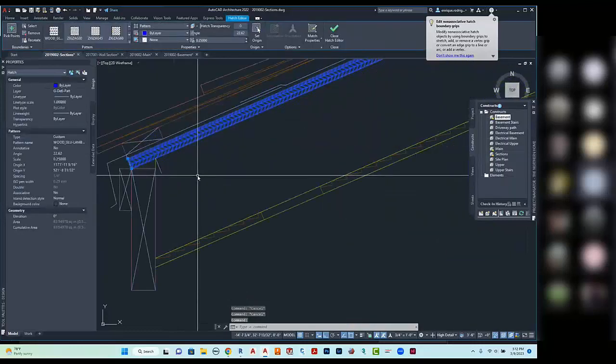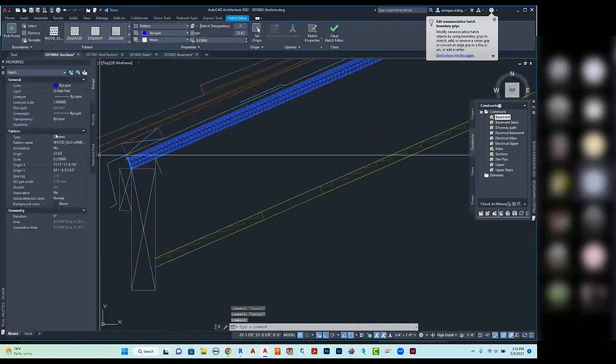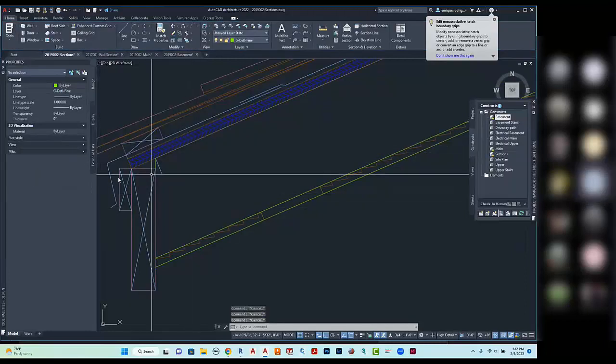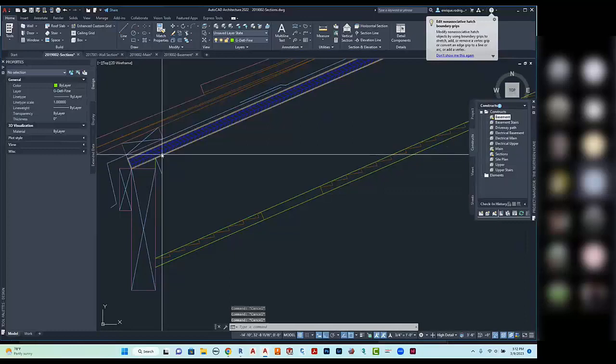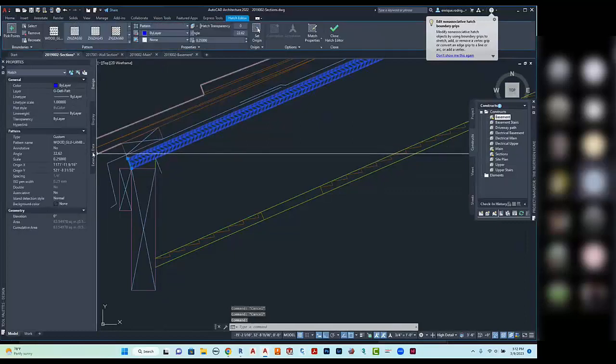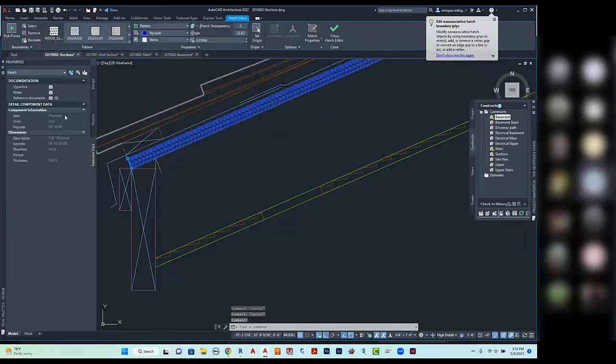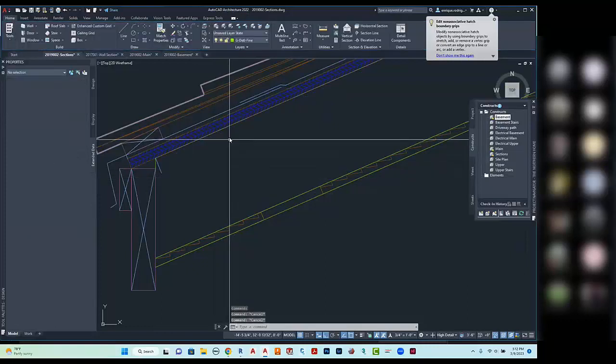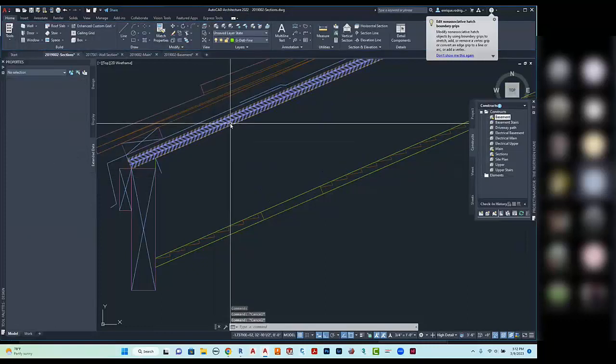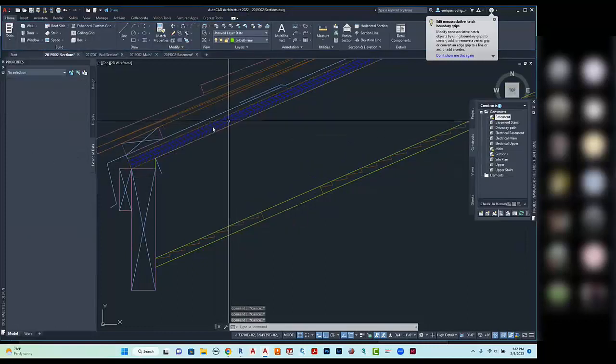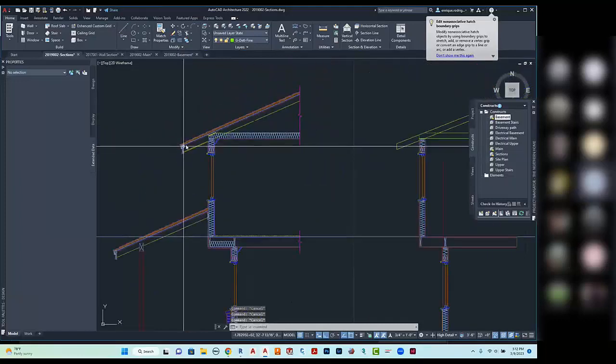Let's add our plywood sheathing on the roof. And if we take a look at here, it really doesn't give us that much information. But believe it or not, if you were to highlight it and go to extended data, it's going to tell you what it is. Keynotes there, plywood, inch, tells you it's 5/8 inch plywood. So it does almost exactly the same thing as if you hover over it. So we know what we need there.